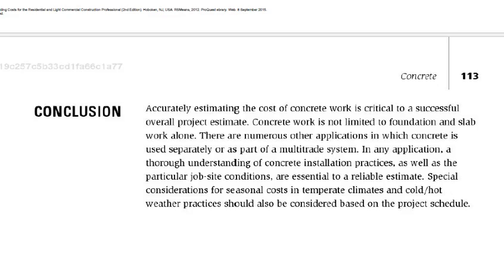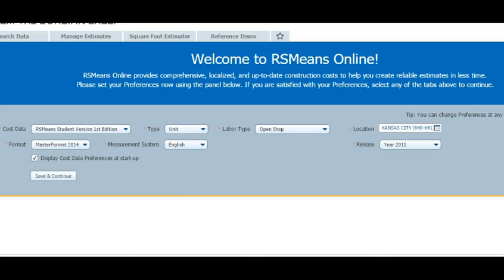And remember, most of all, I think, when you're scheduling a project, time is critical. When it's done is critical because that can affect temperature. Temperature affects the quality of the concrete, the workability, how you get the job done. As we get into the scheduling later on, I want you to keep that in mind. As you read the chapter, just remember to go ahead into your Means program and take a look at it. And if you haven't gotten into it, it's time you get into it.